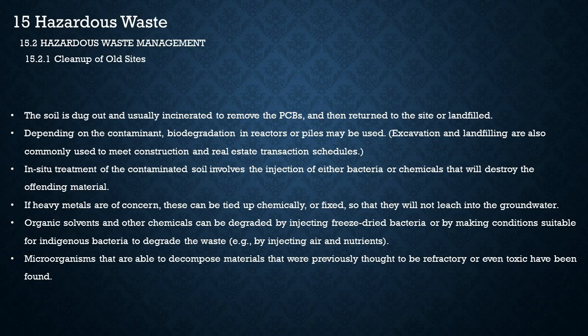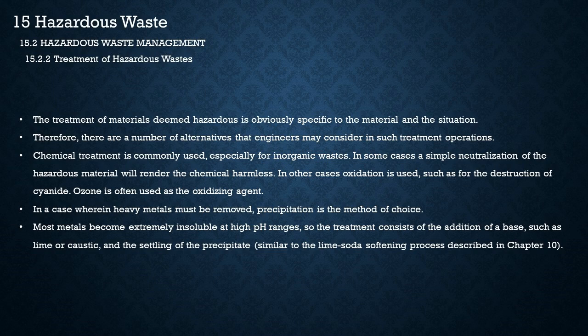In situ treatment of the contaminated soil involves the injection of either bacteria or chemicals that will destroy the offending material. If heavy metals are of concern, these can be tied up chemically or fixed so that they will not leach into the groundwater. Organic solvents and other chemicals can be degraded by injecting freeze-dried bacteria or by making conditions suitable for indigenous bacteria to degrade the waste, e.g., by injecting air and nutrients. Microorganisms that are able to decompose materials that were previously thought to be refractory or even toxic have been found.